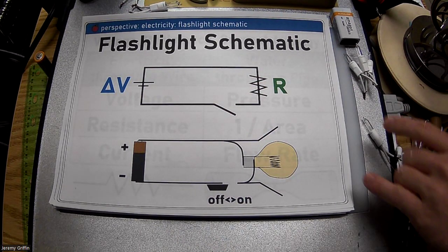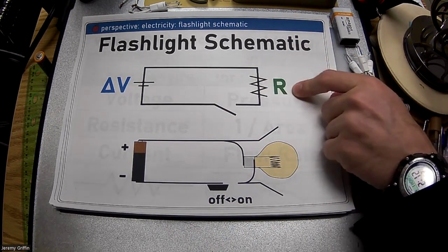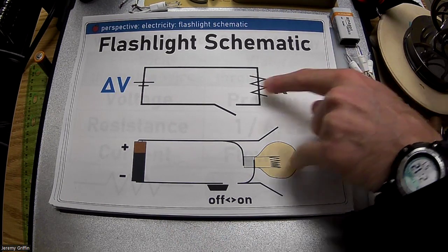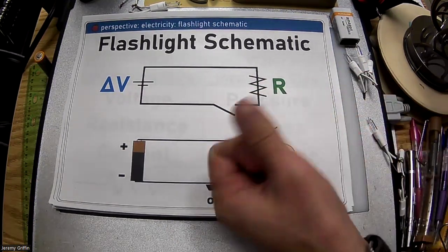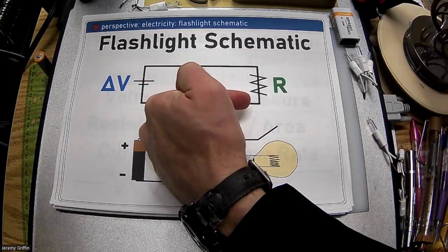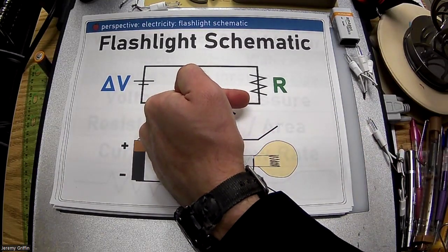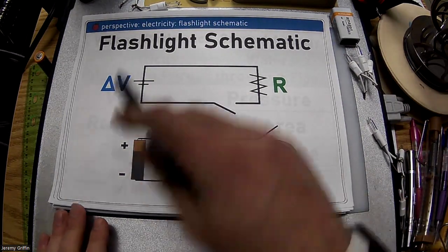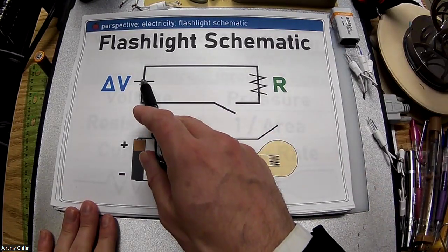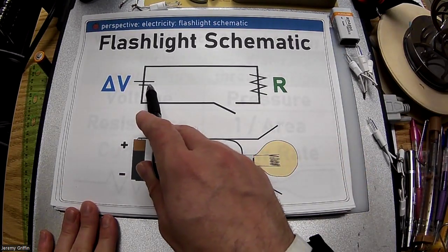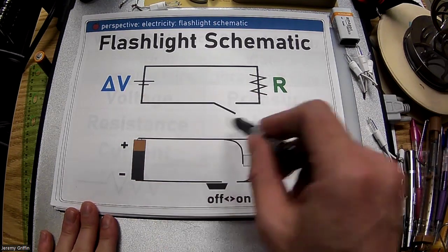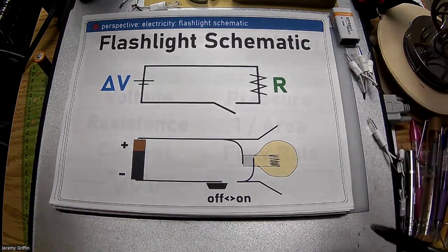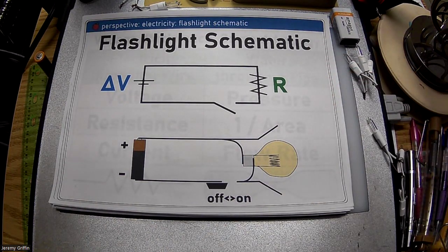And then this jaggedy looking symbol, we'll call that a resistor. My classic go-to example could be a light bulb with a filament. If you see something like that, it could be an on-off switch. If you close the switch, you create a closed circuit, and that's turning it on. If you open the circuit, that's turning it off. To make the circuit work, you need a wire that connects the positive to the negative terminal of your battery in this case. It needs to go all the way around, creating a closed circuit, and ideally also goes through some kind of resistor, because if it doesn't, it just shorts out. You got all that?